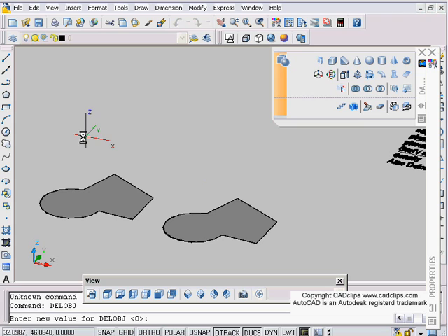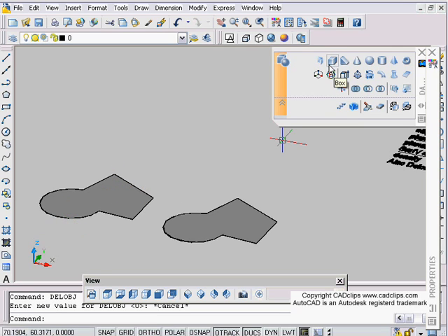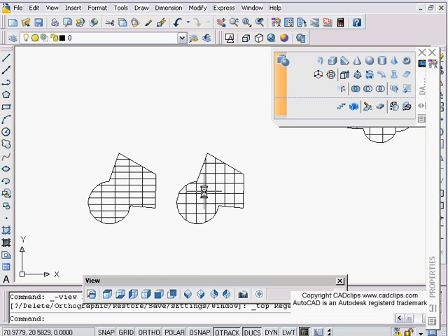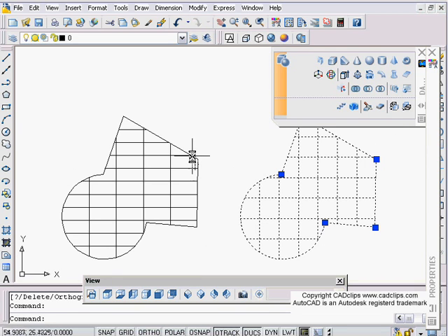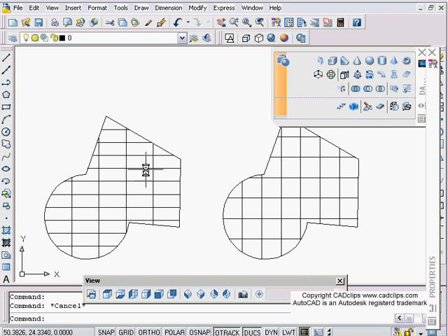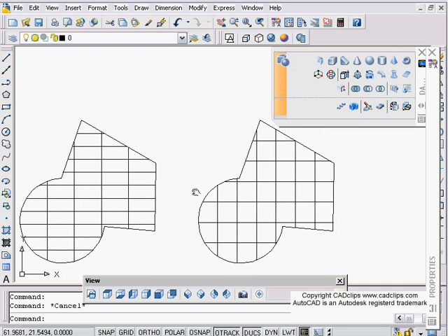That's been set to 0, which is why I was able to erase the solids and be left with those surfaces. So I'm going to switch back to a 2D wireframe and go back to my top view. All I've got here is two planar surfaces that I created using my planar surface tool over here, and they have different mesh densities, but that is okay.